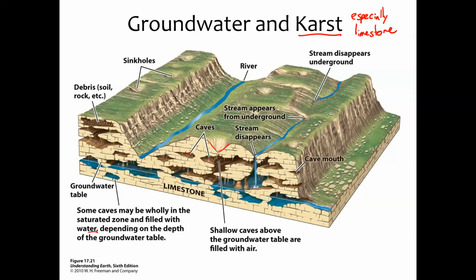So you can see new sinkholes or evidence of old sinkholes as small depressions on the surface. And often those are not filled with water because the water just percolates straight downward. And it's easy for it to enter the cave and then it flows very quickly because these are kind of like giant pore spaces that the water can flow through very easily.